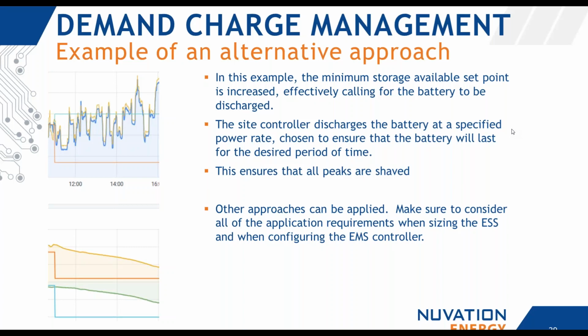There are many other algorithms. For example, we could combine the two and provide peak saving based on the power limit as well as based on the energy limits, and change the choice of how that is done. So the short answer here is make sure you pay attention to your energy storage requirements based on the application, and pay attention to how you configure your ESS to meet those needs.